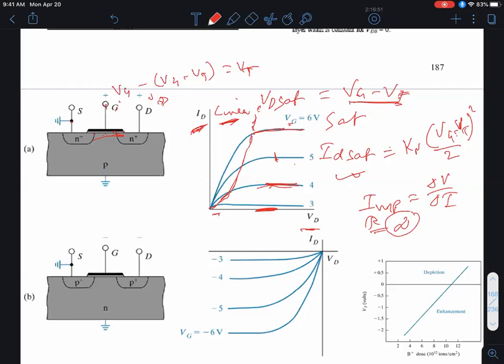Or close to infinity. Similarly, the gate impedance, hopefully there's not much tunneling leakage current. So the gate resistance is also very, very large, close to infinity. And that's what makes a MOSFET so attractive for large scale ICs. You consume very little power because you have a high input impedance and high output impedance, okay? Everything is capacitively coupled, all right? One bad thing, however, is this output characteristics depend quadratically on the input voltage, okay? And that then gives you nonlinearities of gain between the input signal and the output signal.